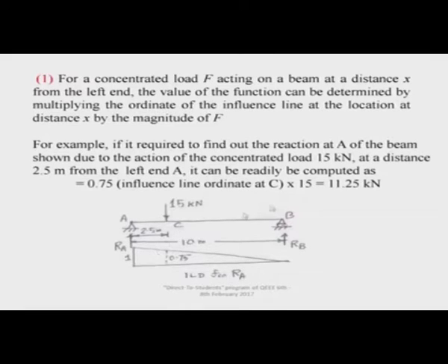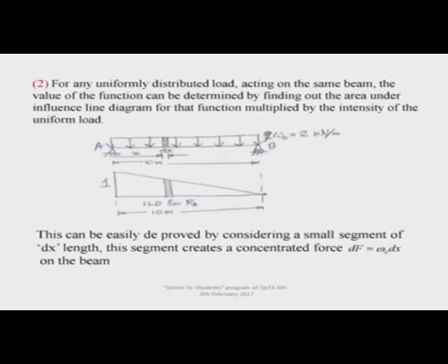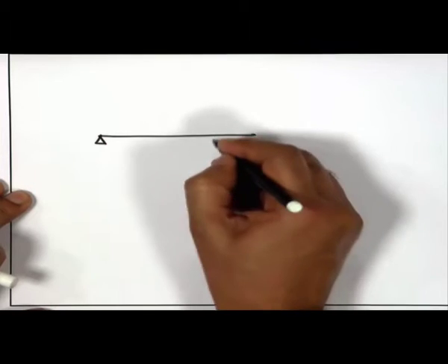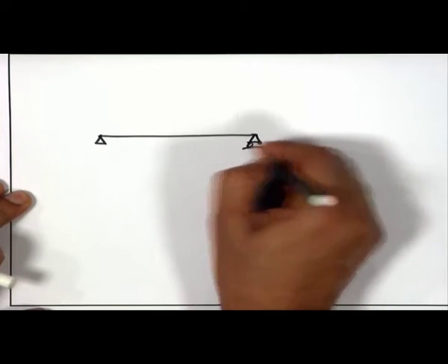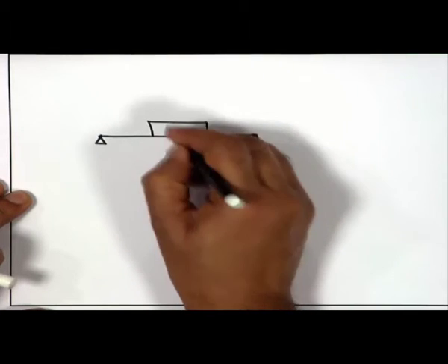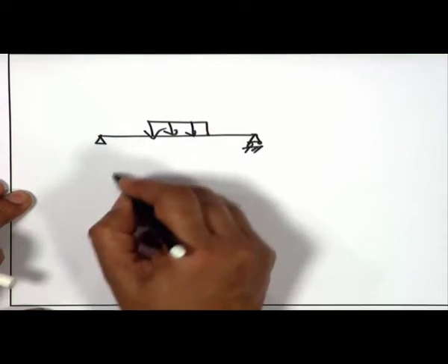So, it is the load multiplied by this particular influence line ordinate which will give that effect there, not anywhere else. And also we have iterated that for uniformly distributed load, it is the area of the influence line diagram which will be useful. If in case the load actually is not distributed fully, but if it is distributed partially,